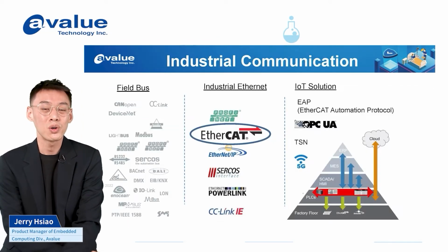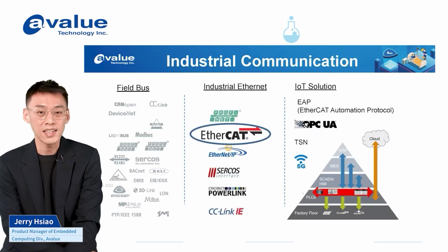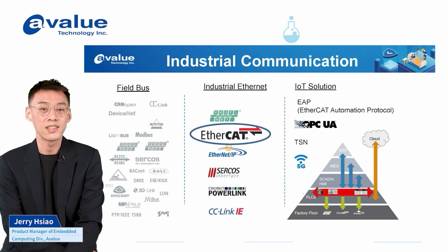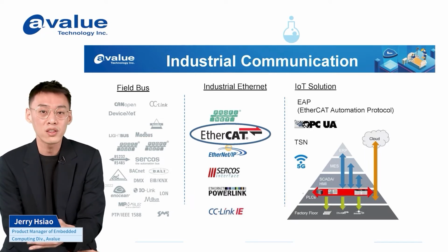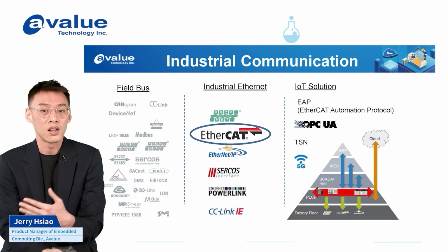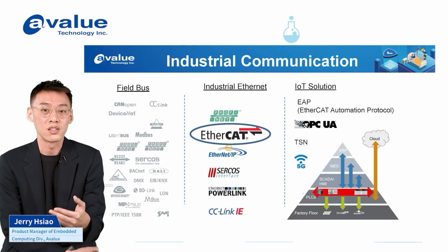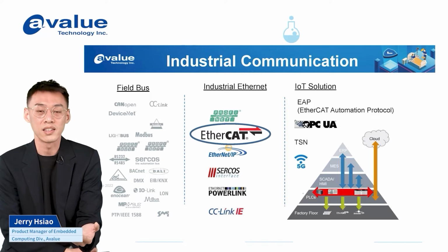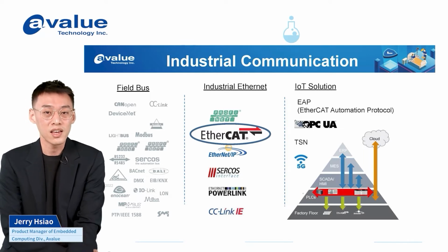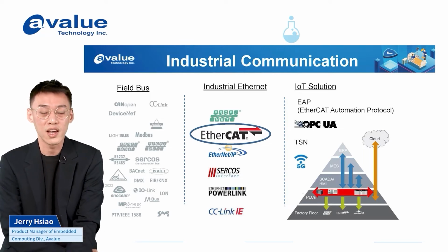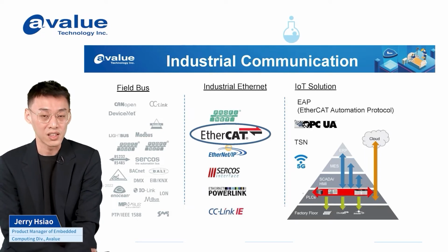So what exactly is EtherCAT? EtherCAT is a protocol that was proposed by Beckhoff and has been used in the market for more than a decade. Apart from the old fieldbus protocols such as CC-Link or CAN bus, EtherCAT is a newer technology for Ethernet specifically in automation.